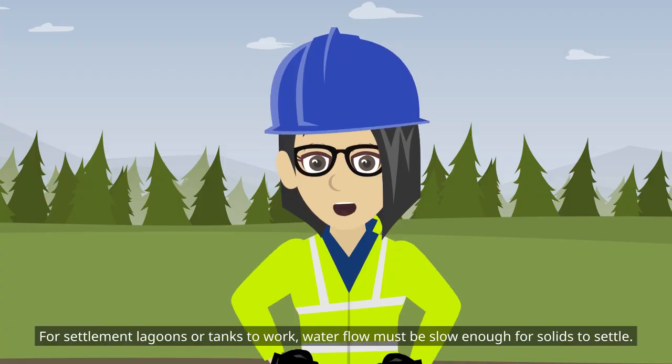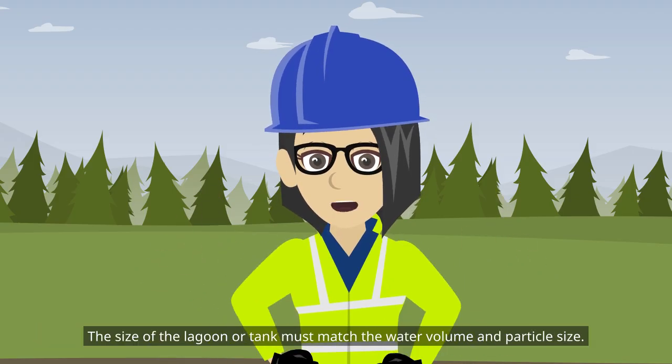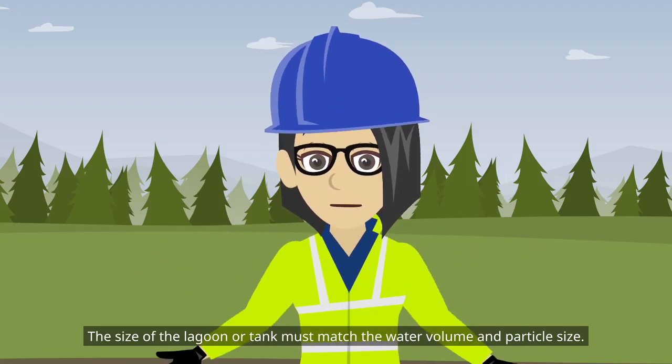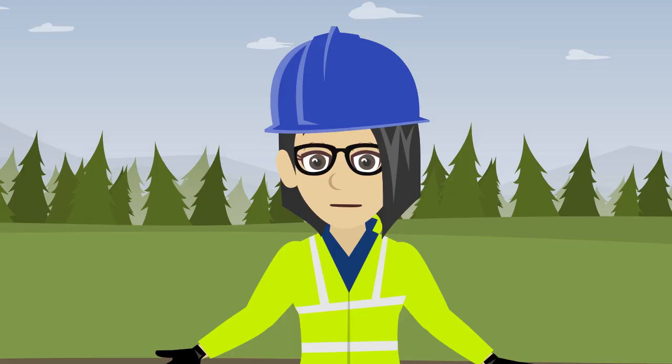For settlement lagoons or tanks to work, water flow must be slow enough for solids to settle. The size of the lagoon or tank must match the water volume and particle size. Smaller particles take longer to settle, so larger volumes need bigger lagoons or tanks.